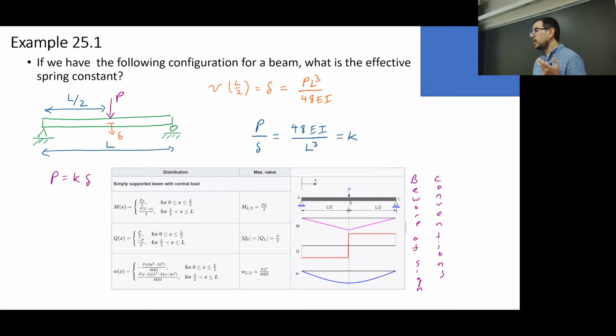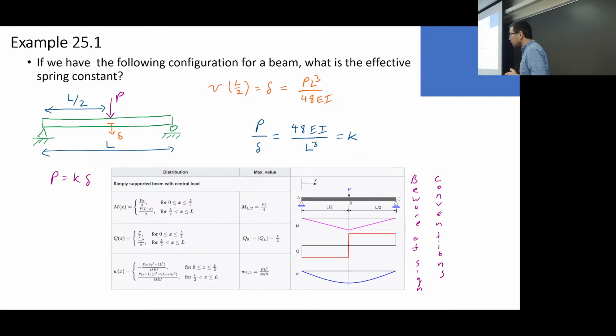We can see it's not the cross-sectional area of the beam, but it's the second moment of area of the beam that's going to limit the moment, or then limit the deflection. Okay. And if you make it longer, the deflection goes with a factor of L cubed. Okay, or with the cube, a factor cubed of that.